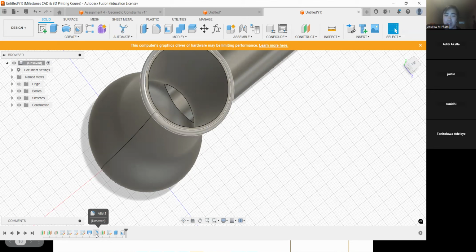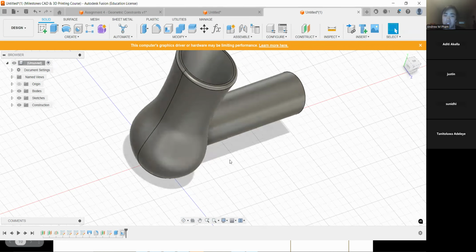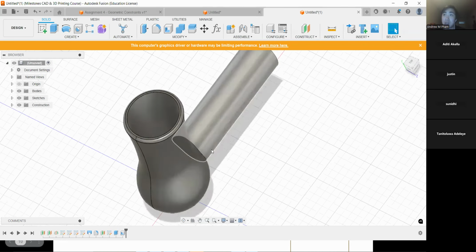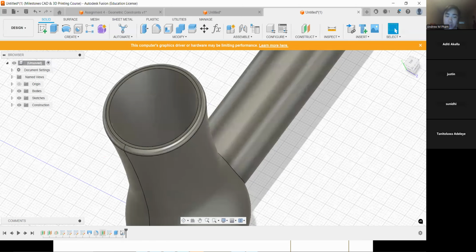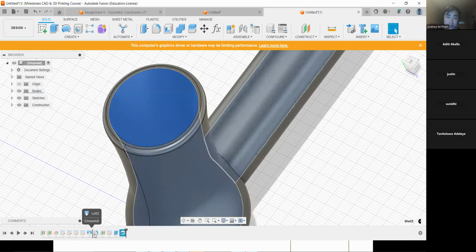If you were to accidentally fillet both sides of the shell, it's not going to let you push the shell forward. The reason is, if you can't push the shell forward, it might be limited by the fillet, because if you try to move the shell in front of the fillet, it's basically like moving what they might call a parent feature before the child feature, right? Here, I'll just do it real quick.